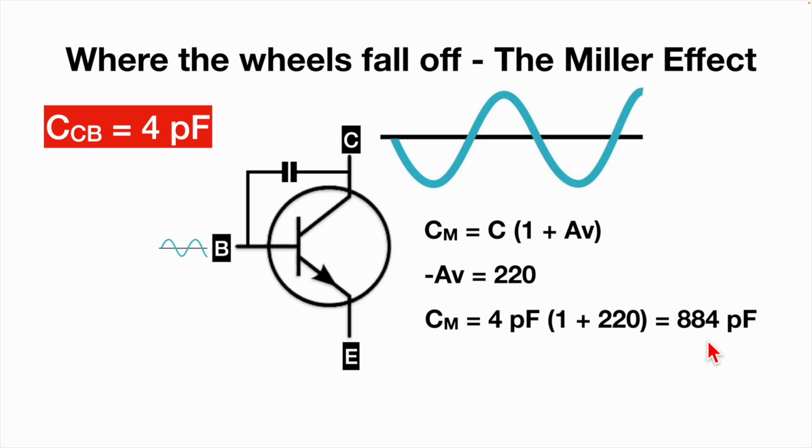And that is precisely what we're seeing in my amplifier, and we'll dig into this in just a moment. That's a problem because my amplifier ticks all 3 of those boxes, right? It's an inverting amplifier, it's got a high voltage gain, and I'm using it at HF frequencies. So that's why I've got such a problem here.